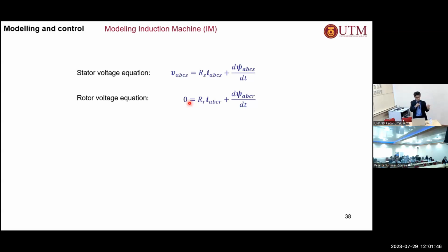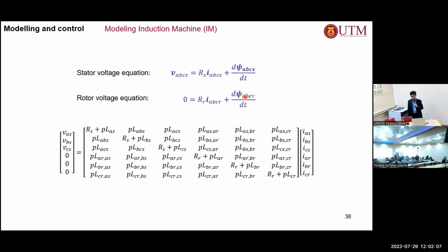The rotor obtains its power through induction, which is coming from the stator. So again, this is the stator voltage, stator current, resistance, and then we have the rate of change of the flux linkage, which is according to Faraday's law. If you have a rate of change of the flux linkage, then you are going to induce a voltage. So if I write down the equations of this, I will end up with something like this. If I expand that, this is the stator voltage, the stator current, the rotor current, and the rotor voltage, which is 0 for squirrel cage. And then we have a bunch of mutual inductances and inductances, right? And then we have the stator current and the rotor current there.